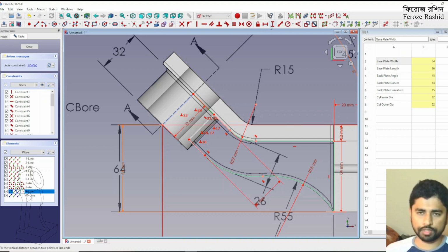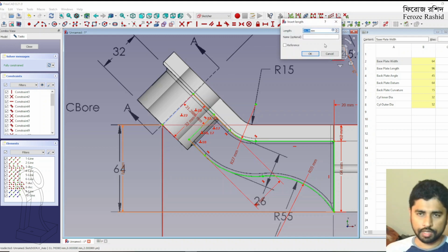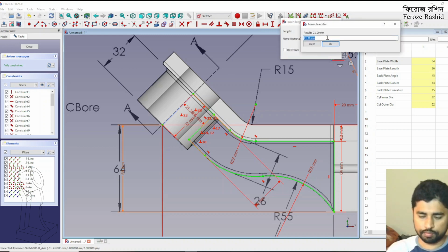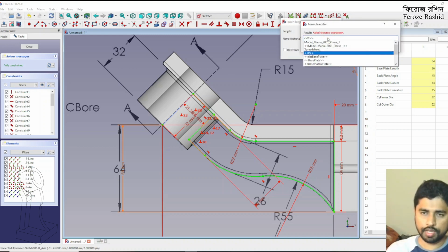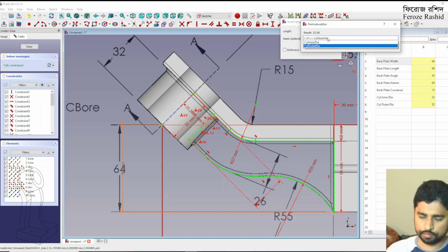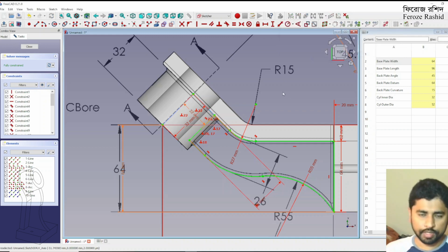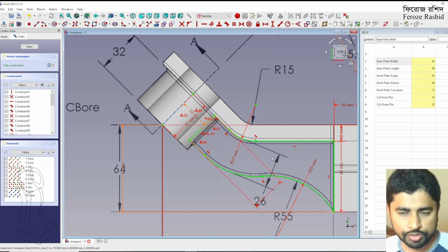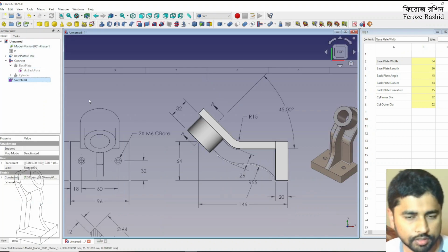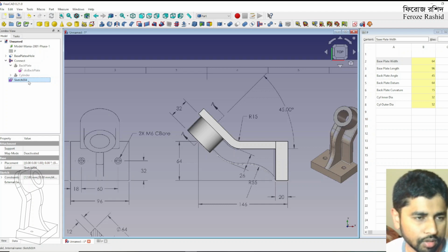So what I want to do is take that and make it cylinder outer dia divided by 2 minus, I may say, 4 millimeter of overlap. I want to do that. Okay, that constrains the whole thing, and let's pray that it will work.